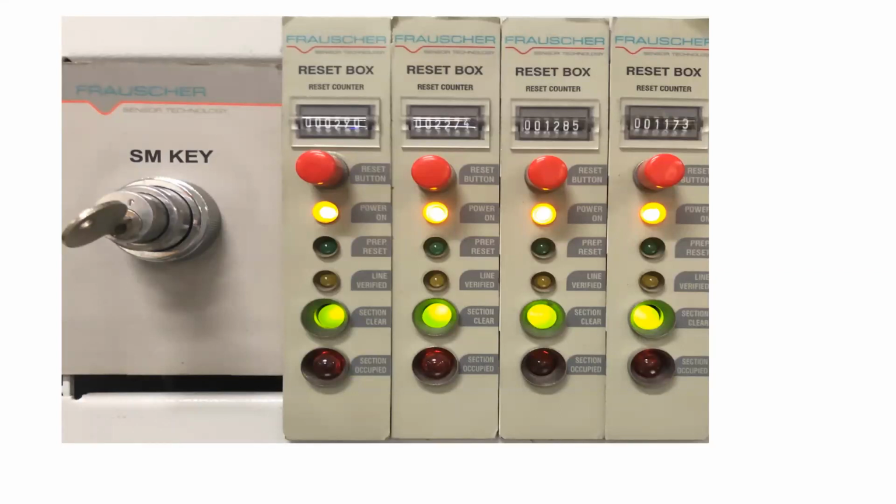Mr. Ravi Sharma has asked, I have a doubt. Yesterday, you said that armor should be earthed at each end. During field work, someone said to me that if earthing of the cable is done at different earth pits at different locations, then a potential difference might be present in the earth pit values, which can cause current in the cable. I hope that means the question is earthing of one end or earthing of both the ends. Okay, correct.